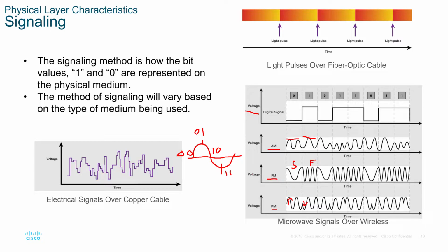One of the things that you may notice is that we do not go all the way down to 0, which is referred to as cutoff, and we don't go all the way to the maximum voltage, which is referred to as saturation. We work in between those two levels. The reason for this is it makes the switching much faster.